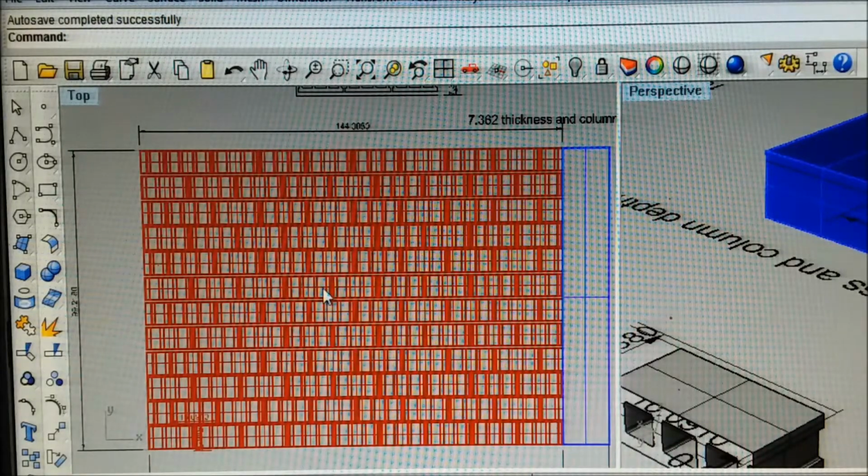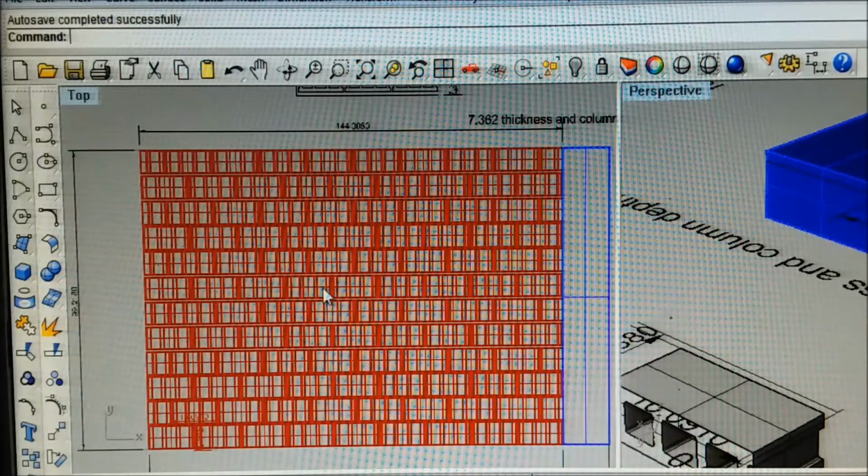practice on a hollow block construction of 12 feet of block before a column. There's a 12-foot column on either side. For the comparison, we have a 12-foot long piece of hollow block, and then we have a column that's 16 inches wide. The thickness of the column is a 5-inch block plus 2 renders on either side, with a standard render, which is 3 centimeters to the side.